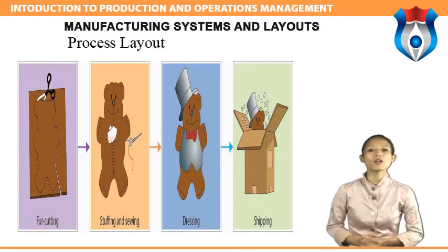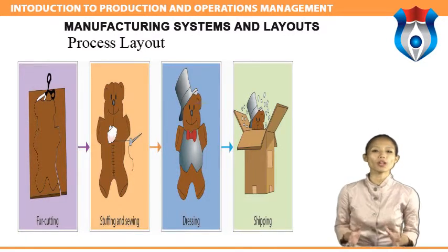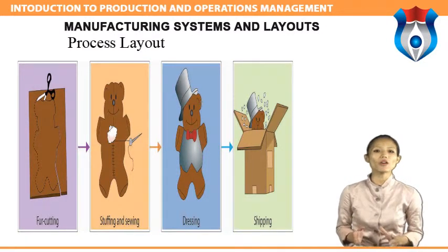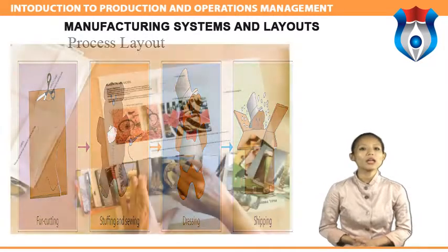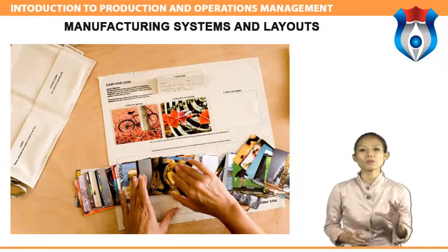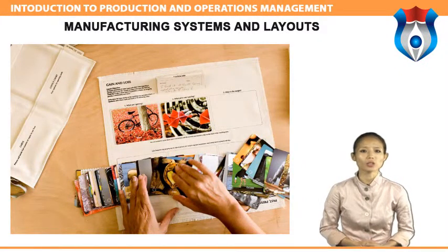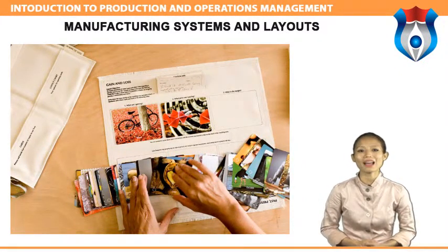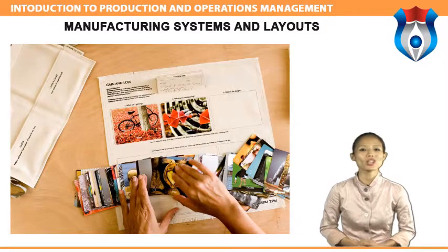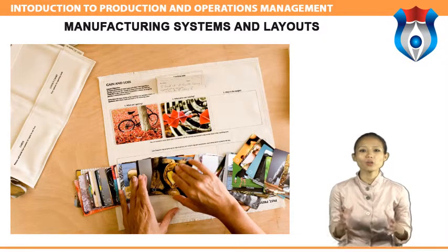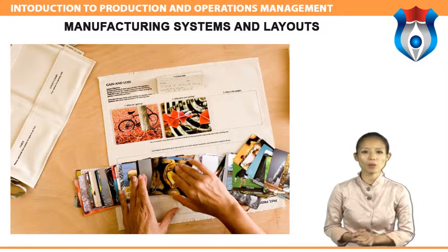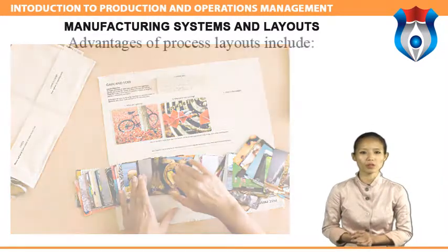Process layouts are facility configurations in which operations of a similar nature or function are grouped together. Improving process layout involves the minimization of transportation cost, distance or time. To accomplish this, some firms use what is known as a method grid, where subjective information is summarized on a grid displaying various combinations of department, work group or machine pairs.